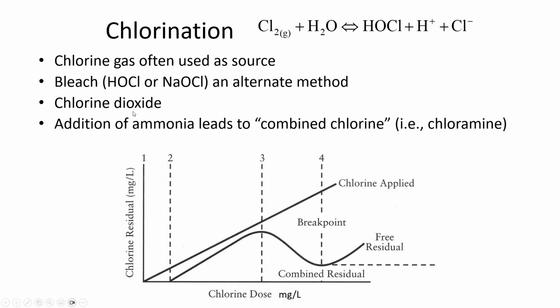Chlorine dioxide is nice because it can be generated from salt. They can just use salt and then an electrical process that forms chlorine dioxide gas on site. And so you're bringing in a raw material that's very stable. It doesn't break down over time like bleach does. When you've got liquid bleach at high concentrations, it just naturally decays, even if you're not exposing it to anything. Whereas if you bring in salt, it's not going to decay, it's not dangerous, and so you can generate the chlorine dioxide on site. Of course, it's using electricity, so it can be costly in that sense.